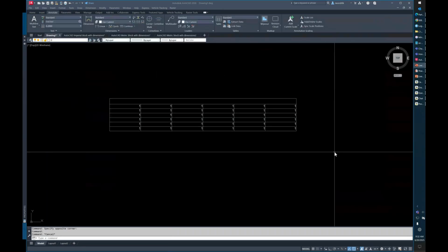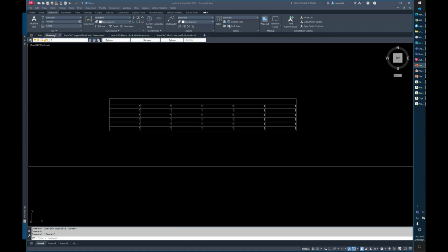All right, so let's go. All right, so Karen, I will get to you in just a second. Paul, what is the best process to bring in architecture drawing to civil drawing? That is the $1,000,000 question. Because your architect drawings are always coming in thinking that they're inches when they're actually feet. And when you bring it into civil, it's always scaled up by a factor of 12.